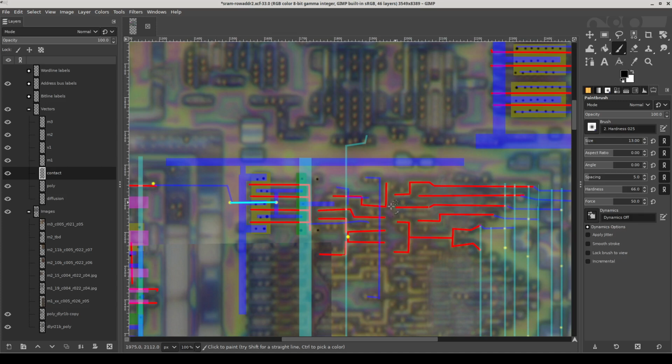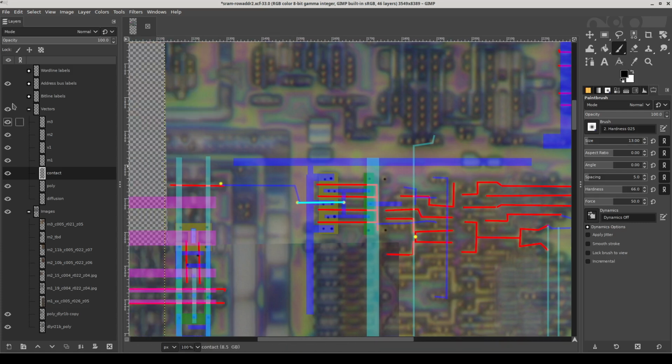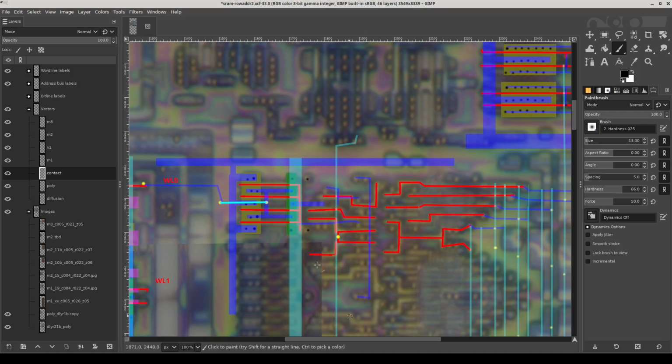So coming from here, it comes out from this AND circuit and then goes into this giant inverter right here, which is presumably to increase fan out. This small circuit here probably doesn't have a whole lot of drive strength, and then it continues on out to the word line right here, which I've helpfully labeled, and goes on to the actual bitcell array. Now, noting that there is an inverter on the output, that does mean that what we've got here is actually going to be a NAND 5, not an AND 5, since we need to have a second inversion for the word line to be in the high state when the row is selected.